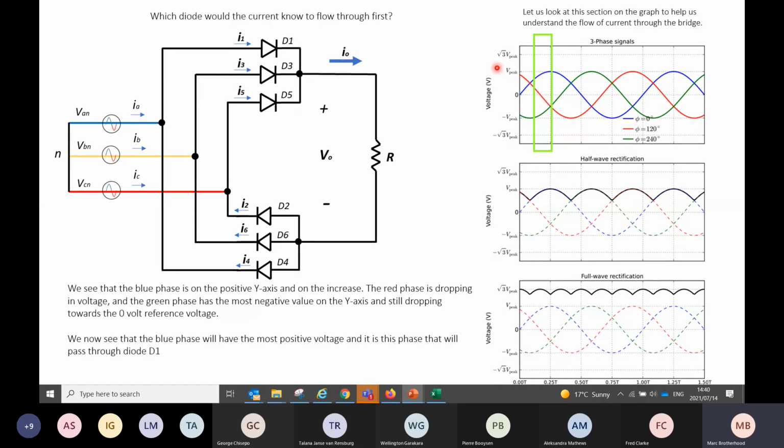Let's say this is, say, 400 volts. It'll be more, about a 400 volts peak. We're looking at about 520 volts here. So imagine this line is 520 volts, and here's no voltage. We can see that in this window, the red voltage is busy dropping to 0, and now it's going negative. Negative, by the way, doesn't mean it's not going to shock you. You touch this here, you're still going to get zapped.